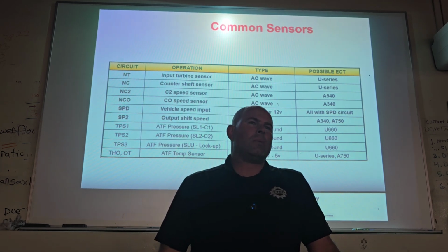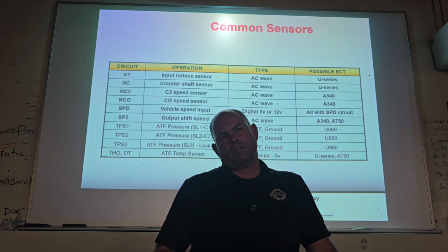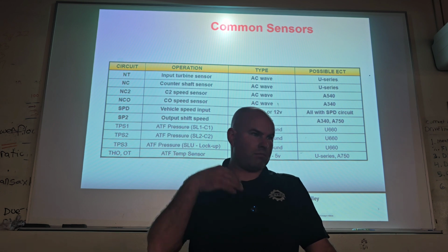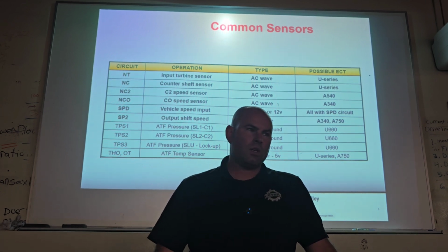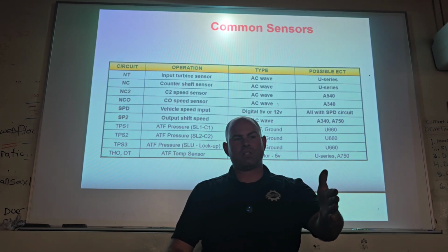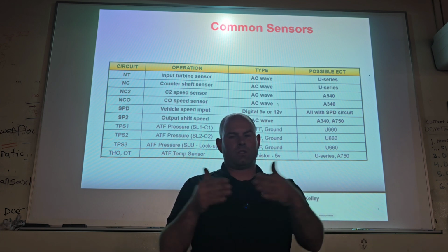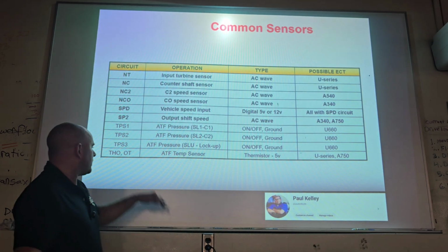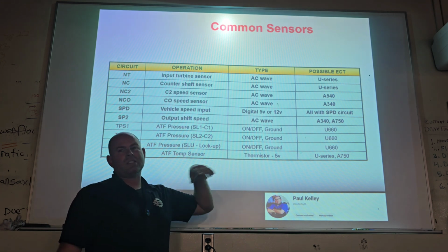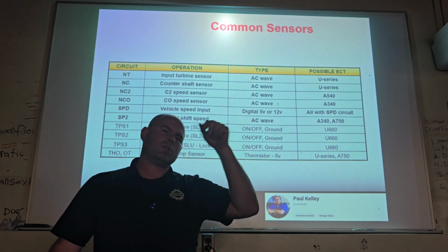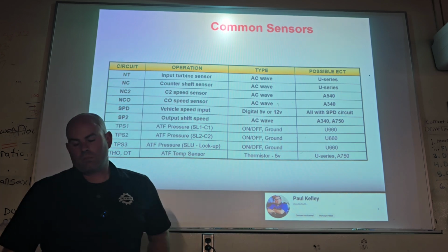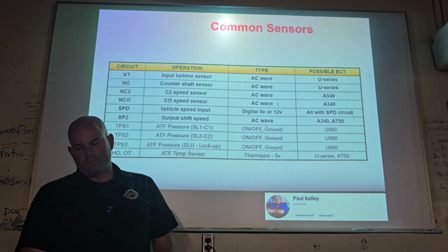If you jump in there and you see the temperature's reading 300, come on, give it back to me. That's a short. That's like no resistance in the circuit, so somehow the wire feeding the thermistor and coming back to the ECU is just jumpered in there somehow. Okay, so everything you learn about that's going to be the same. This is the same for intake air temperature, coolant temperature sensor. Thermistor circuits are really pretty easy once you get them.